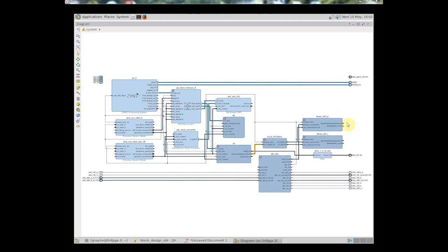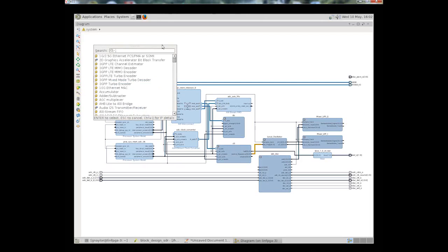So now we have here and here the I and Q amplitudes of our antenna signal at the frequency defined by the local oscillator. So one thing that would be useful to do now is to define a signal level monitor which monitors the level of the signal at this point here, either here or here. The level will be the same. So we will try and average this signal and determine a signal level. So to average we'll use an accumulator.